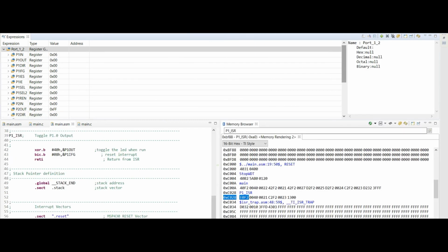Okay, now we're on to the interrupt side of this demonstration. Interrupts work differently than polling. Interrupts are set into the memory. They're used when an event is sent to the CPU. What that does is cause the CPU to stop whatever it's doing and do the interrupt. And when the interrupt is completed, it will go back to where it last was and continue on into the program.